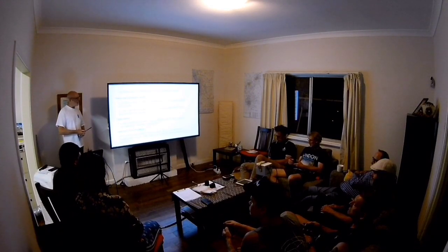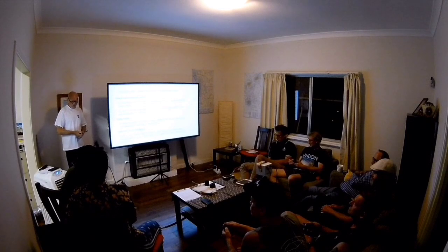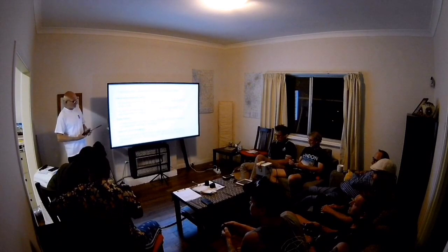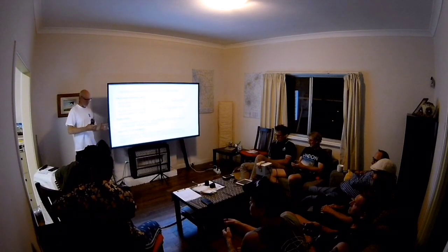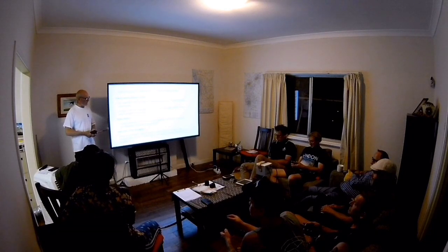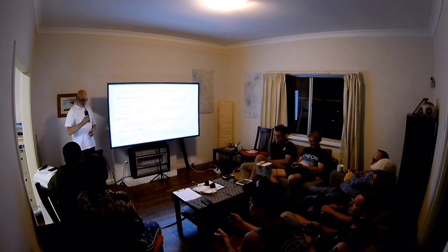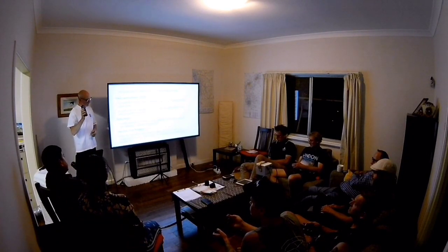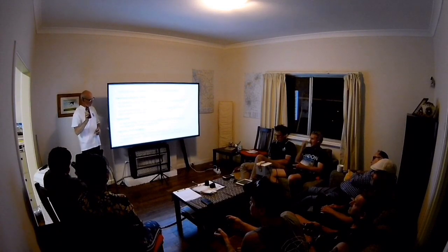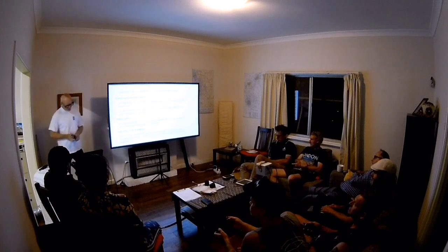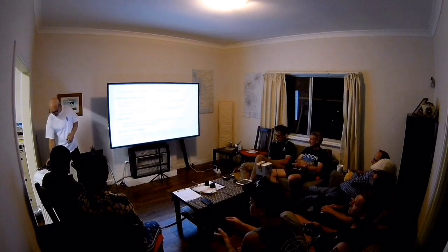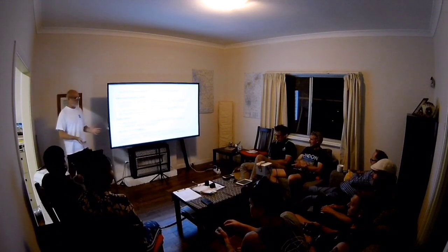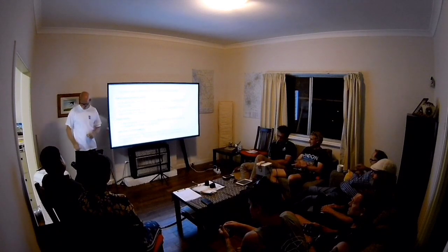An important part of your pre-flight checks is to check the status of any fuses or circuit breakers in that system. You may have fuses and things attached if you're connected to external power on your handheld radio. So if you are using external power, again, make sure that that power source is live.